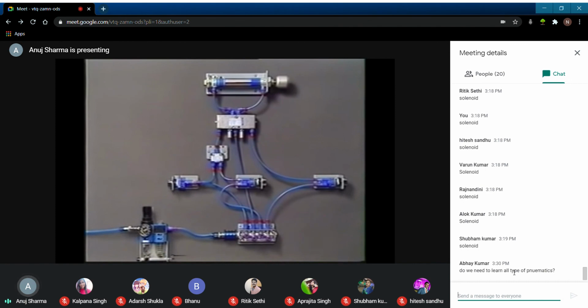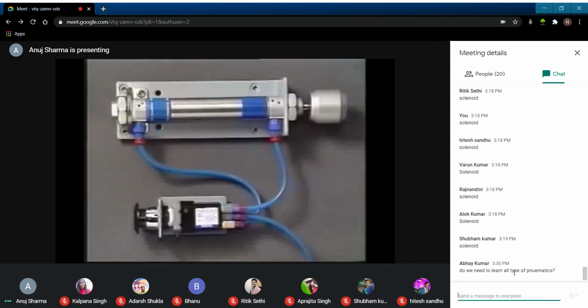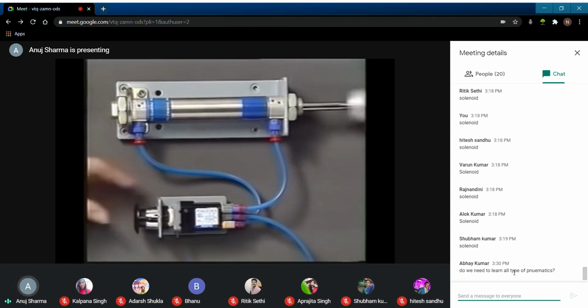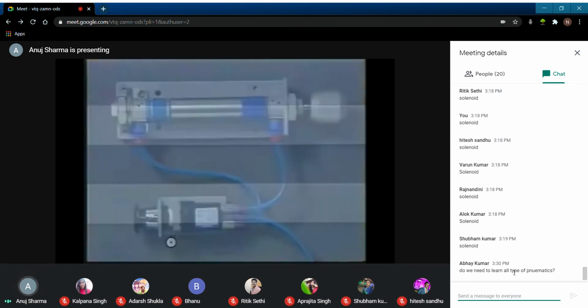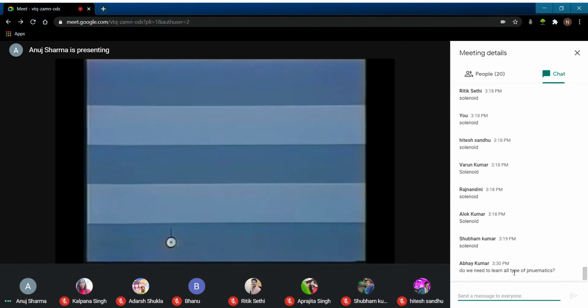The fifth level contains the actuators, but not all control circuits contain separate components for each level. In simple circuits, one component may provide the functions of multiple levels. This push-button actuated directional control valve provides the functions of signaling, logic, and direct control. Next, let's look at the 5 levels using ISO symbols to represent the components.